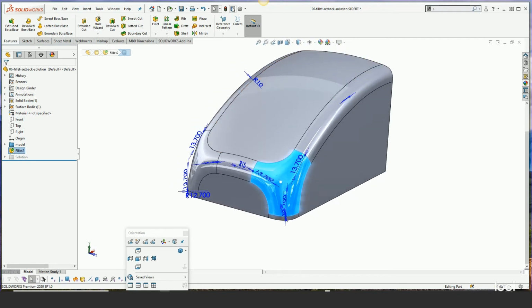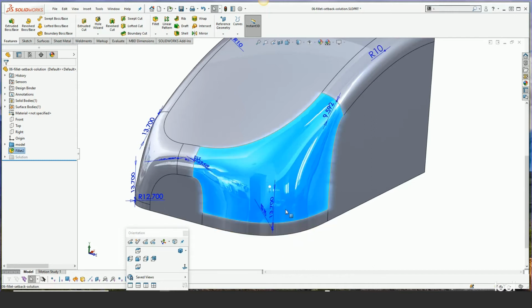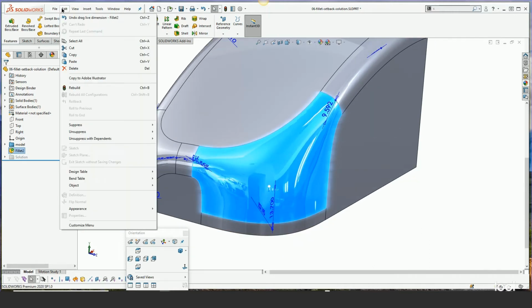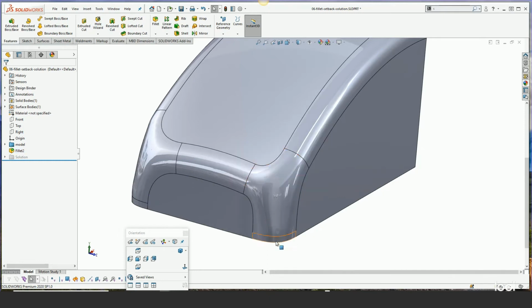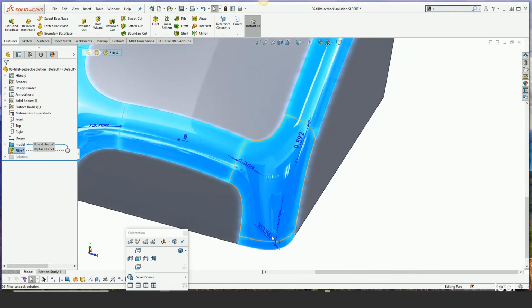Now, it's kind of interesting with Instant 3D on. You can actually start pulling on these values and start to play with it to tighten it up a lot. And that's what I want to do here. Actually, that was pulling my radius value. I want to highlight it again and pull this meatball up a bit. Let's get it a little tighter.